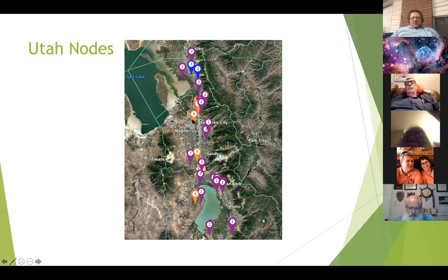When you look at this, you'll see some of these say 2, some of them say 5, some of them say 3. That's talking about the specific frequency band that they're using. So either the 2.4 gigahertz band, the 3.5 gigahertz band, or 3.4, or the 5.8 gigahertz band. And a lot of these, you can't really see it on this picture, but if you were to expand this one here where it has the orange 5 at Lake Mountain, there's actually 4 2 gigahertz routers up there as well, and they're all kind of connected in together, so they're all talking to each other. But it only shows the 5.8 gigahertz one on this diagram.